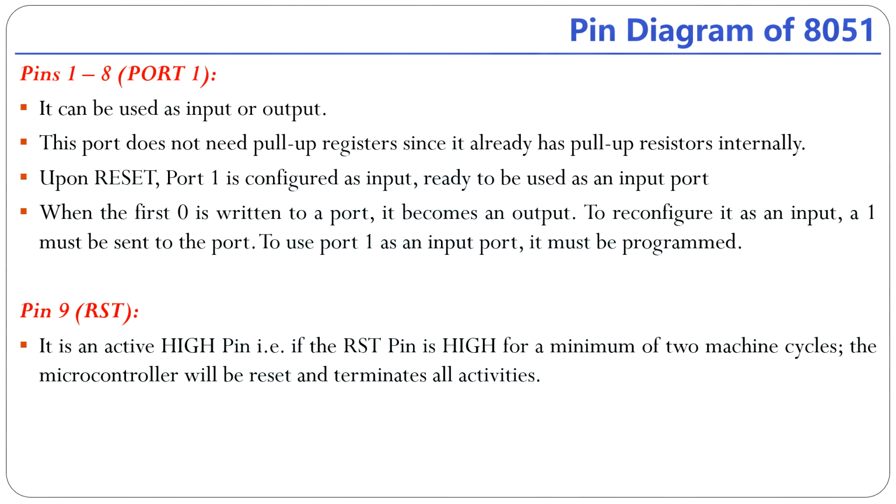That means in order to activate reset pin, you compulsorily need to provide a high level signal for a period of 2 machine cycles on the RST input of your 8051 microcontroller. Then only your microcontroller will enter into reset mode and terminate all internal activities.